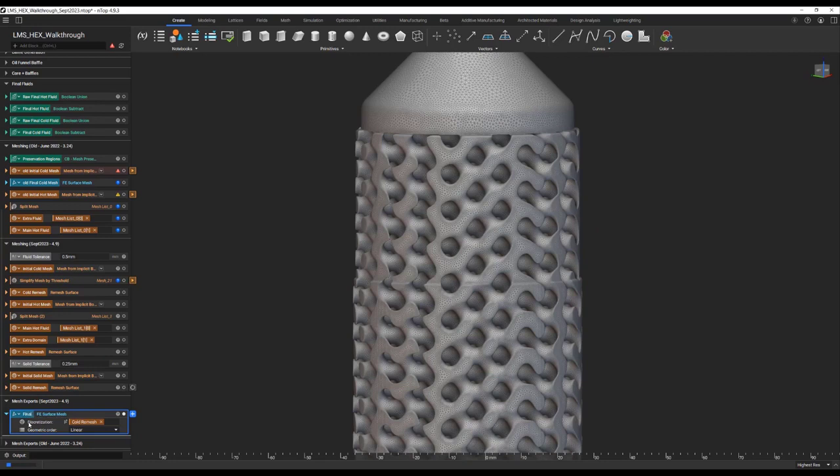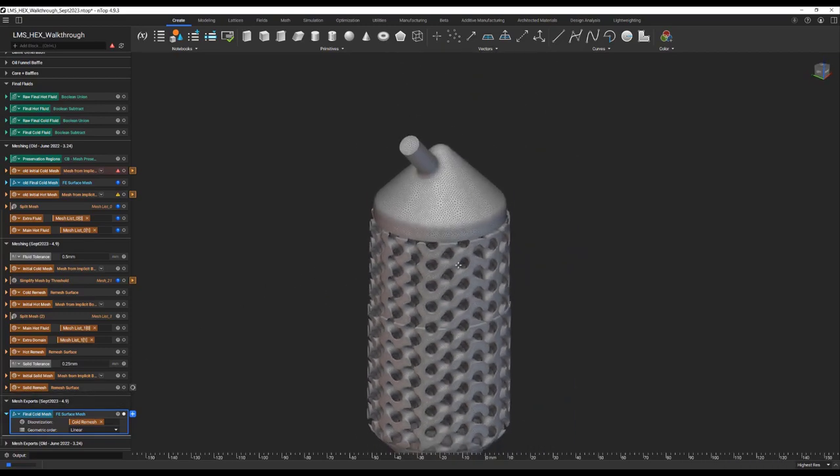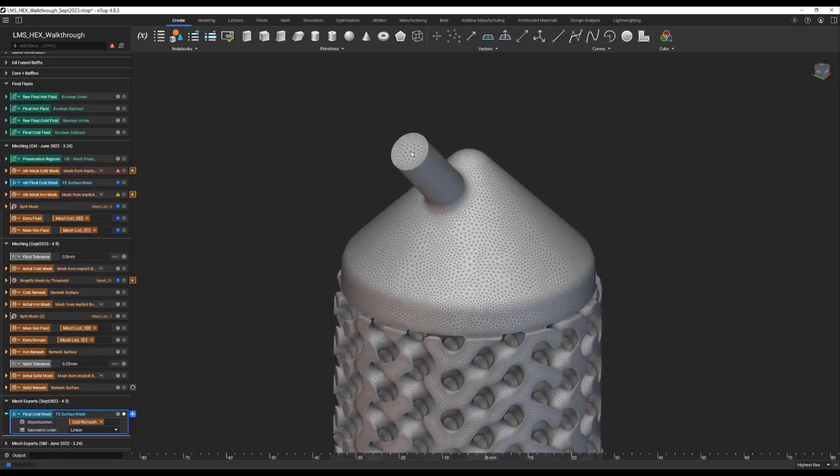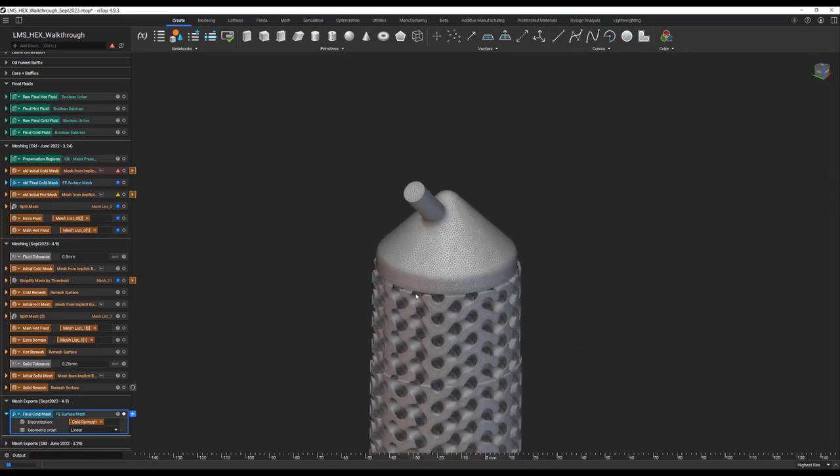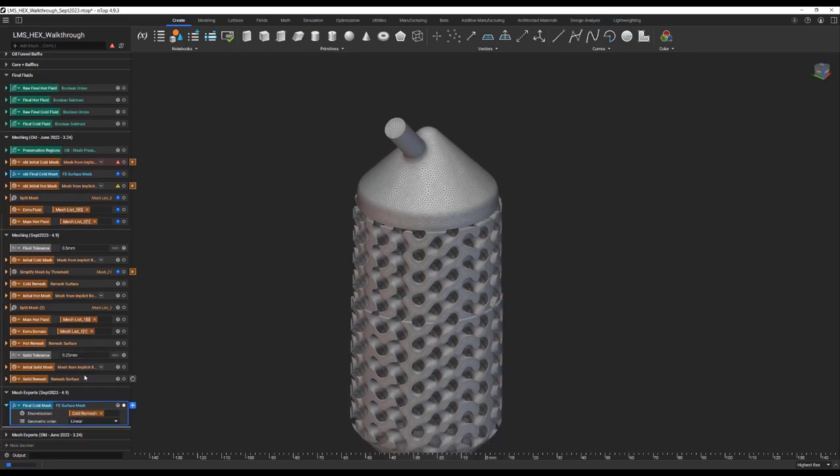In previous videos and tutorials that you might have seen up until this point, to get to ANSYS Discovery, we generally exported an STL mesh, and then in Discovery, we would use the faceted selection tool to snap to, let's say, the edge that we define here to create our inlet and outlet boundary conditions. With some updates on ANSYS's end as well as ours, we can now export an MSH file, and those boundary condition locations are going to come along with that block.